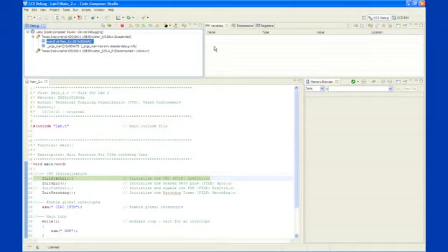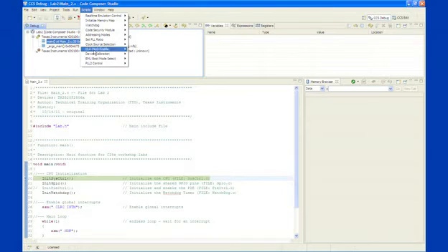In the remaining parts of this lab exercise, the device will be going through a series of resets due to the watchdog timer. So we need to configure the device with the EMU_key and EMU_B mode, so that the bootloader will jump to memory block M0 SARAM at the address of 0000. To set up the EMU key and EMU_B mode, we'll use the script. We click on script, go down to EMU boot mode select, and we will take EMU boot SARAM.